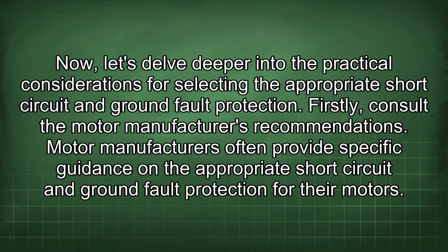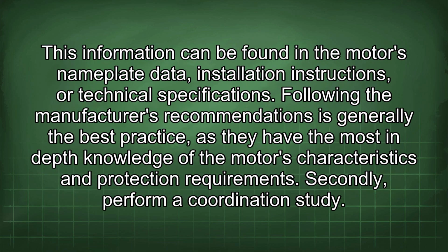Firstly, consult the motor manufacturer's recommendations. Motor manufacturers often provide specific guidance on the appropriate short circuit and ground fault protection for their motors. This information can be found in the motor's nameplate data, installation instructions, or technical specifications. Following the manufacturer's recommendations is generally the best practice, as they have the most in-depth knowledge of the motor's characteristics and protection requirements.